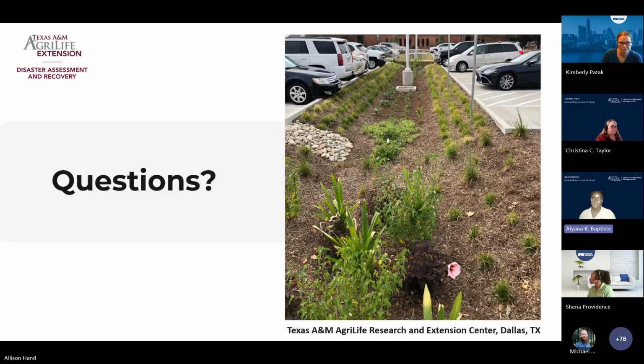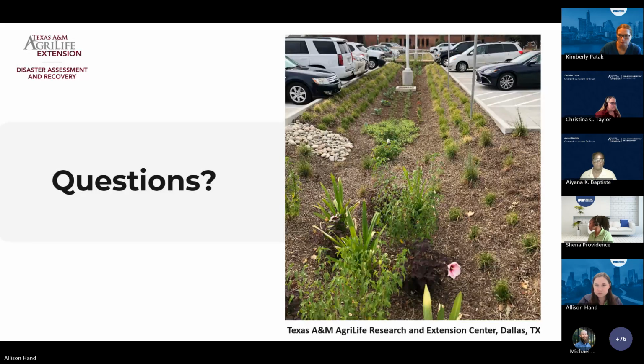And the next question is, can you confirm that bioretention infiltration testing should be done at the bottom, at the interface in native and installed improved soil, versus the surface of the BPM? I think you just answered that. Yeah, so in the implementation guide, we provide a reference to the City of Austin's infiltration practice, and they step you through specifically that it definitely needs to go into the native soil. You have to consider the full depth of your infiltration practice to make sure you're able to infiltrate that depth. And it also provides the number of holes you want to do based on the square footage of your control.